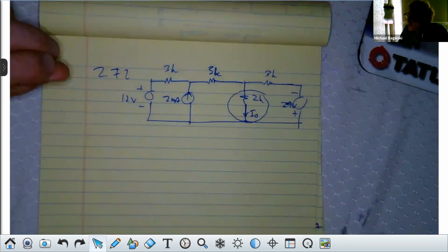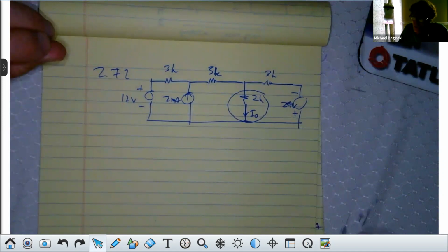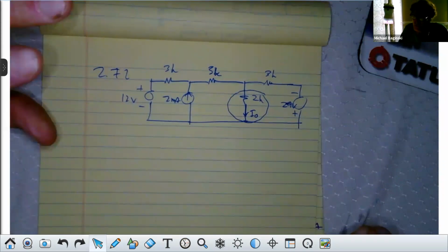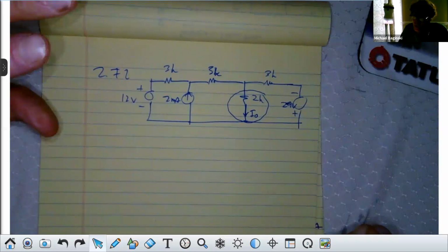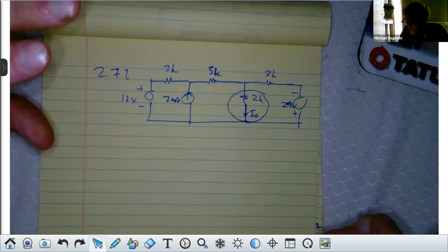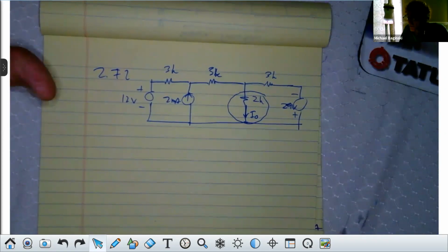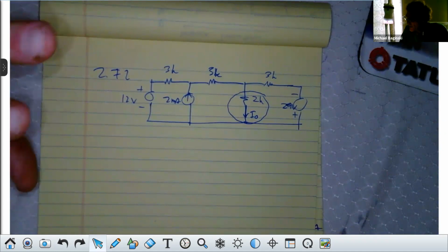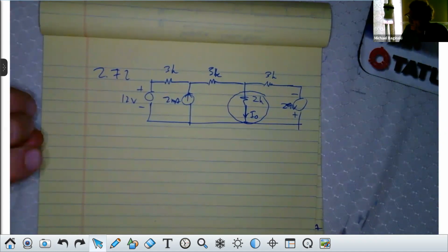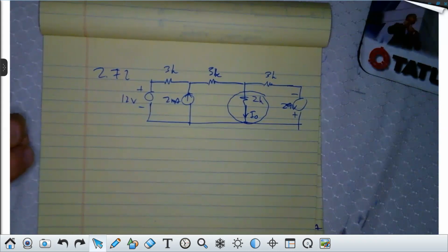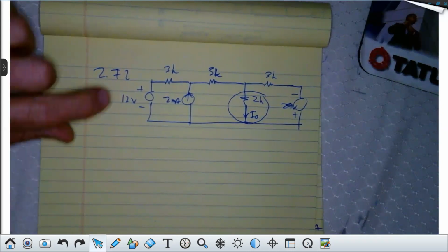So it tells you in the world you're not going to transform that. All right. But here's what we're going to do. We're going to create a Thevenin equivalent voltage source or a current transform of that, which is called a Norton equivalent, without ever doing the usual way we did it, where we take the open circuit and then turn off the sources to find R Thevenin. Do you all remember how we did that with R Thevenin, right? We're not going to do that. Here's what we're going to do. We're going to do source transforms.